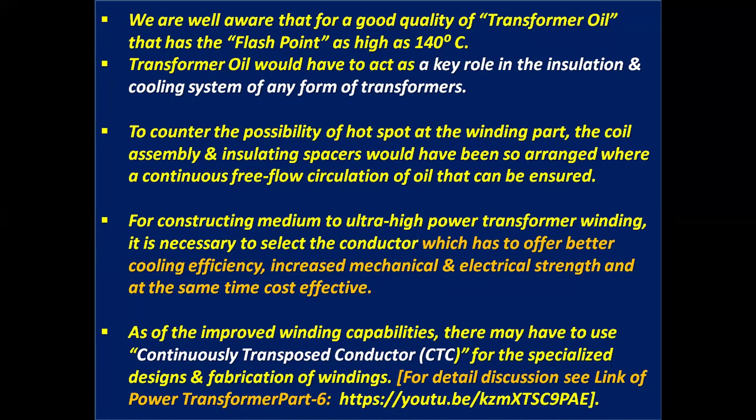To counter the possibility of hot spots at the winding part, the coil assembly and insulating spacers would be so arranged that a continuous free flow circulation of oil can be ensured.